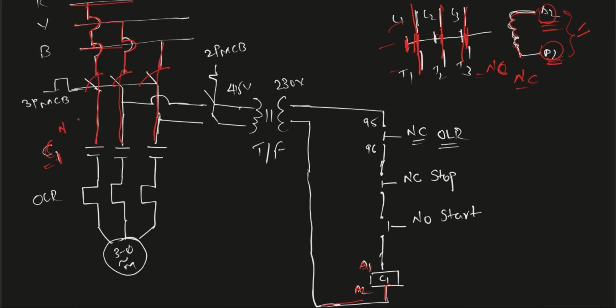These are currently normally open contacts. A1, A2 should get power to close these contacts, and the voltage will pass after closing the contacts. So the voltage is stuck till here. Our motor is still not running because there is no voltage flow. Then we have taken two other supplies to the two pole MCB, right? The supplies are stopped till here. We will manually close the MCBs. MCBs are closed, and the power comes to our transformer.